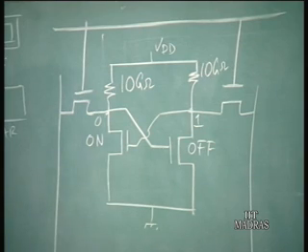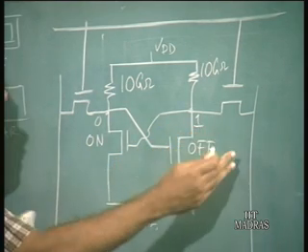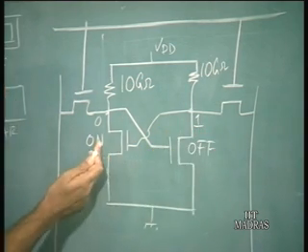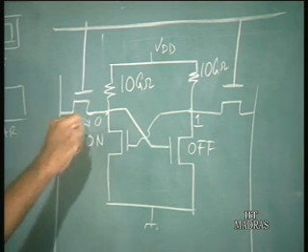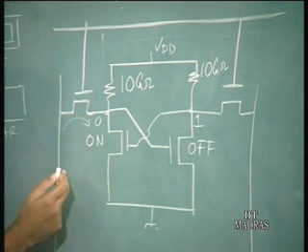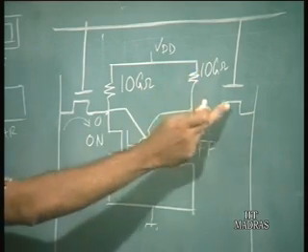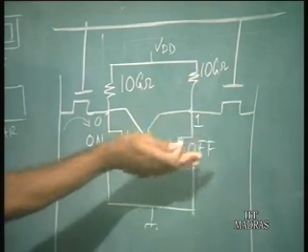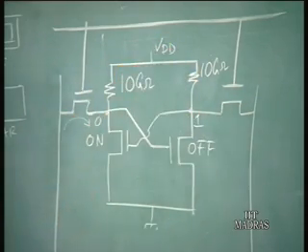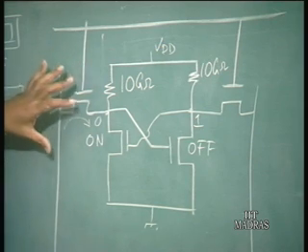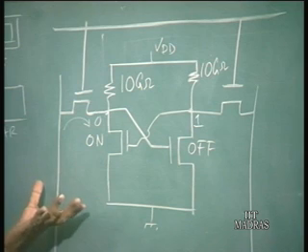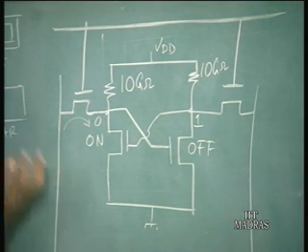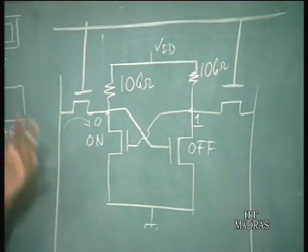If this is the condition, and this particular cell is selected, since this transistor is on, it is going to help to discharge this line voltage, but this cannot be depended upon to pull up the line voltage on that side. So, what is done in this case is that the data lines are pre-charged to VDD, that is the supply voltage, the highest voltage in the circuit.